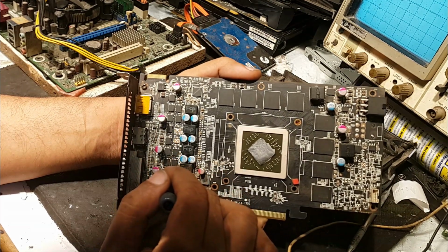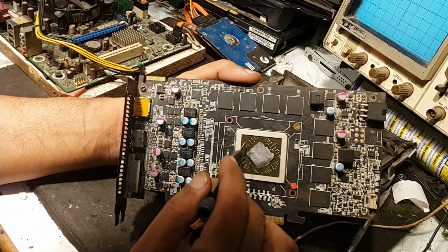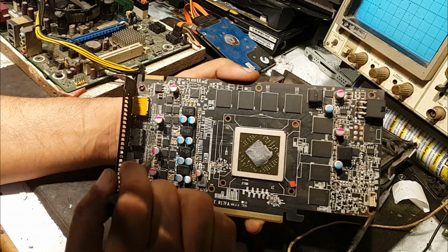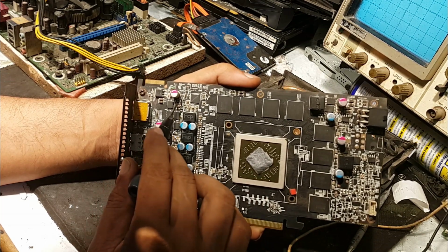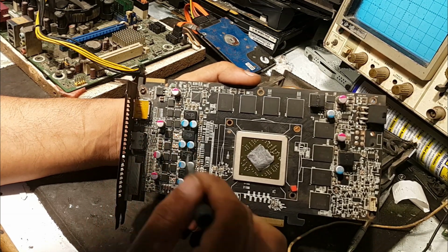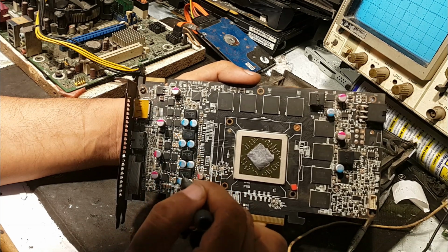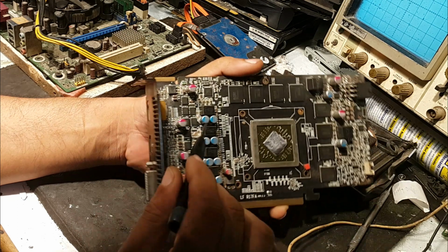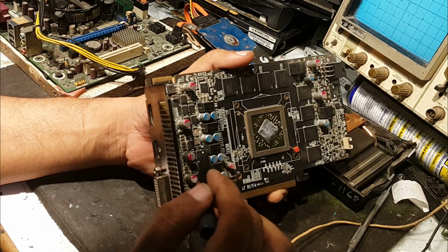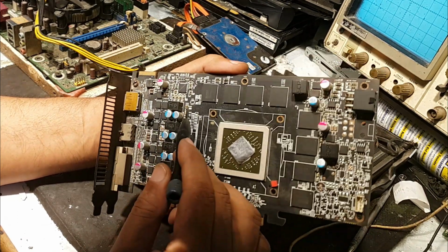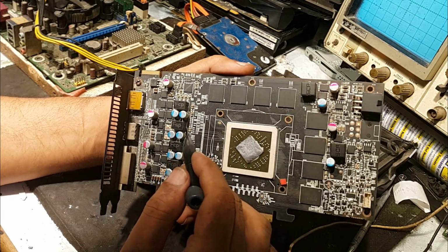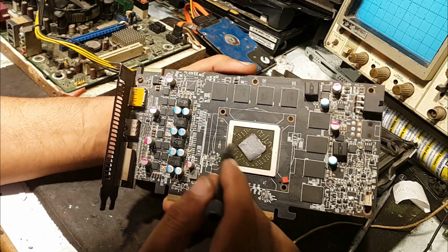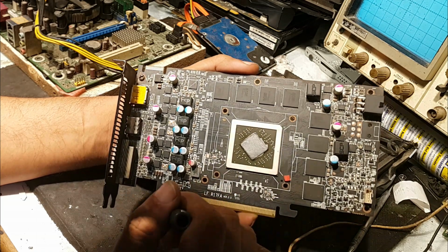It is the main power supply designed for this GPU chip, and these FETs are driving these 4 chokes, 1, 2, 3 and 4, and giving the oscillation on the input points of these chokes, and the output 1 volt is driving this GPU.